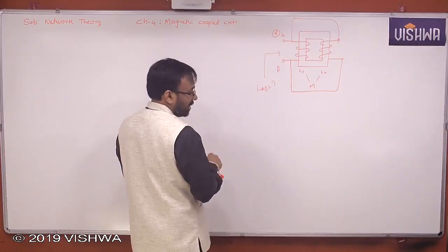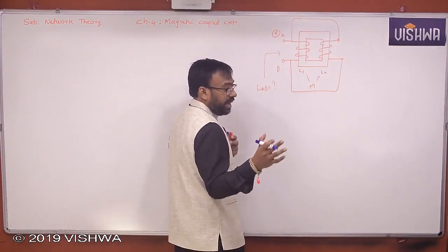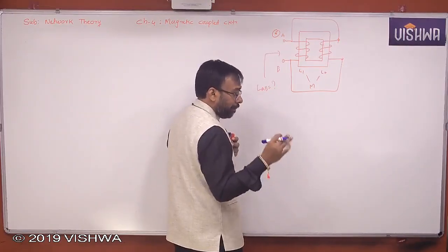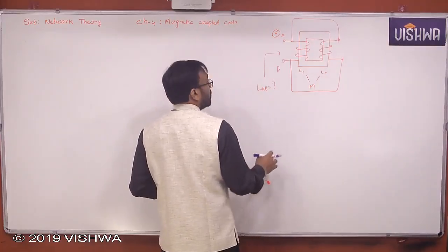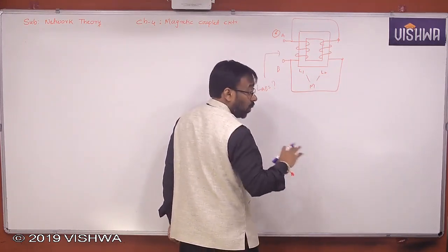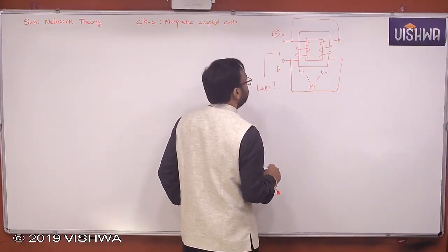So first dots, then Volt-Amp. Remember always LAB or ZAB or XAB in case of magnetically coupled circuits, go for the Volt-Amp method. Okay. Now this is not an ideal transformer because L1, L2 are available. Ideal transformer, no L, no R. Yes or no, all of you? Okay. Well, so now you see.